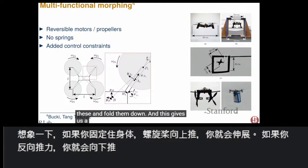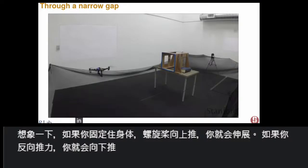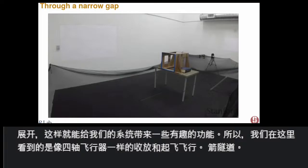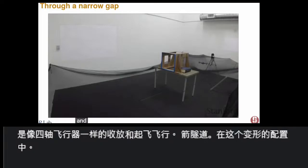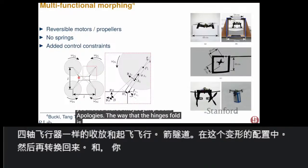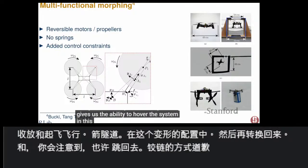And this gives us a system with interesting capabilities. Here we see the drone take off, fly like a quadcopter, and then fly through this narrow tunnel in this shape-shifted configuration. And then transition back. The way that the hinges fold is not quite aligned, so that you still have yaw authority, which gives us the ability to hover the system in this reverse configuration.